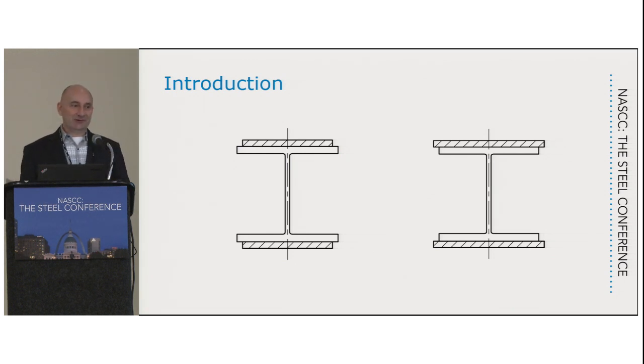We will be limited to axially loaded members. If you want further information on flexural members, you can take a look at this webinar that I'll show you the link to about halfway through the presentation. Generally, everything has to do with flexural buckling, so we're pretty much going to be limited, at least in the discussion, to wide flange shapes typically. All of my pictures show wide flange column shapes. Most of the things that we'll talk about will also apply to other shapes, but you can figure out how to apply those to the other failure modes you can get if you have, say, an angle column where you end up with maybe a torsional buckling or flexural torsional buckling.